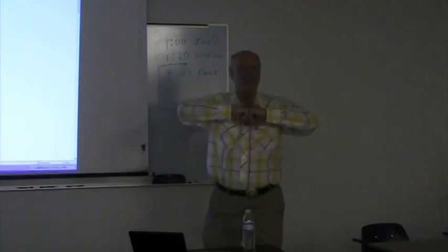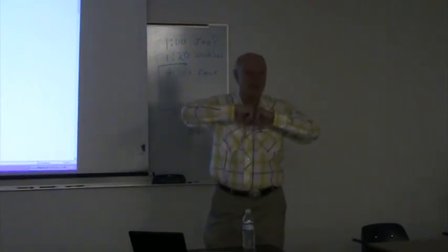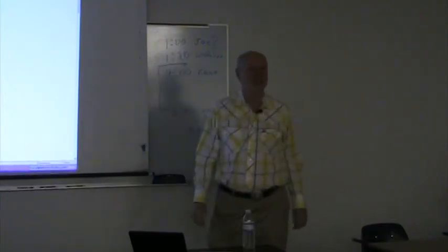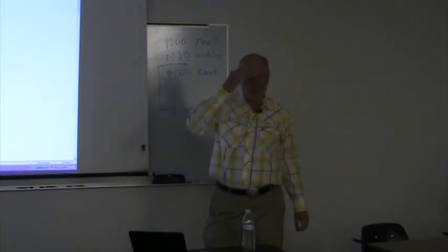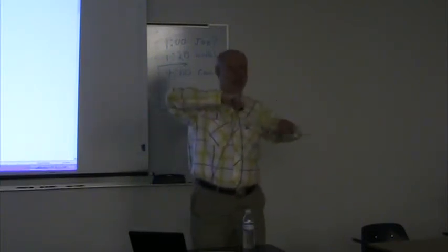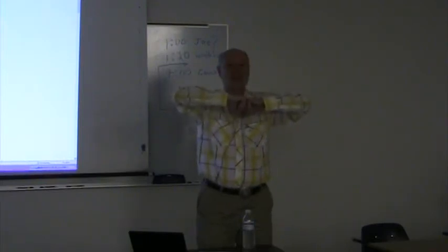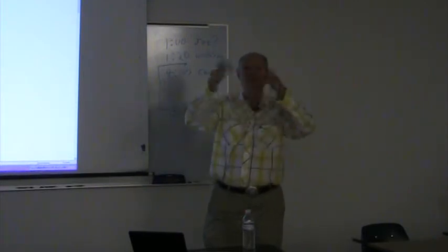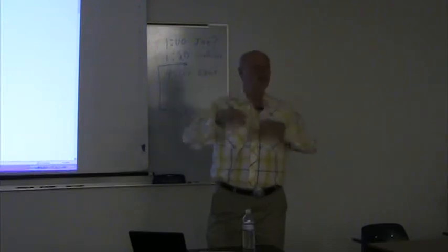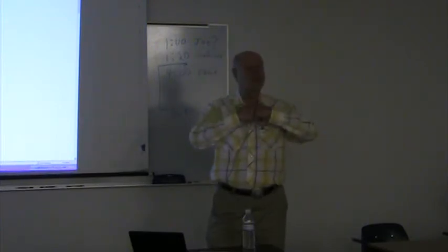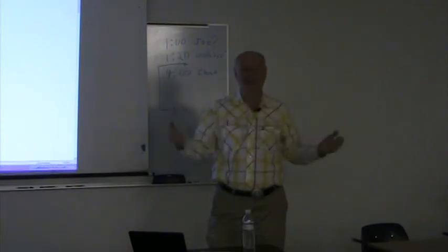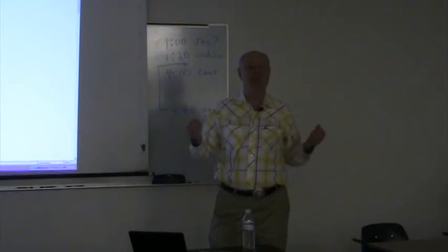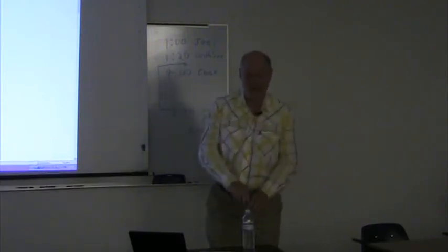And that's an okay thing, because as soon as somebody is written to and switches from reading to writing, the signals propagate just fine. Perhaps a little less obvious is the case where you've got one node writing and another node, its neighbor, writing to it. So you're thoroughly locked up. But that could easily be the case when you're doing a multi-port write. You can't really write to 4 neighbors, but you can write to 3 of your neighbors. And some of those neighbors may be writing back at you. And again, you've got to lock up until somebody switches modes and decides to read. And that's okay. It doesn't hurt you. It doesn't even draw any power. This is a perfectly benign situation. Unless it is unintentional and there is no mechanism for correcting it.